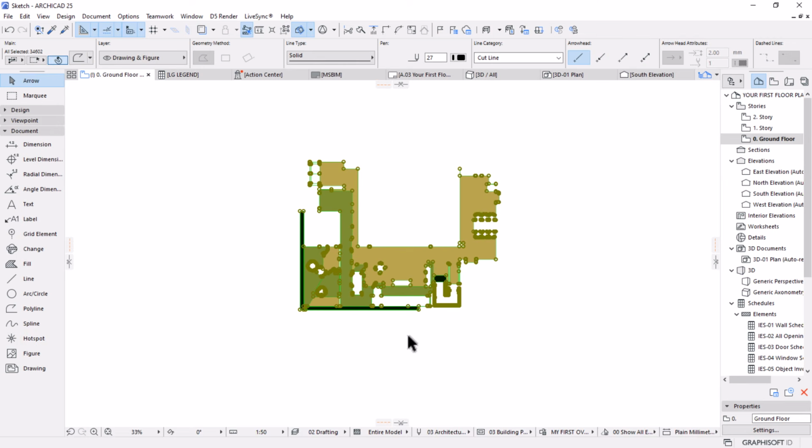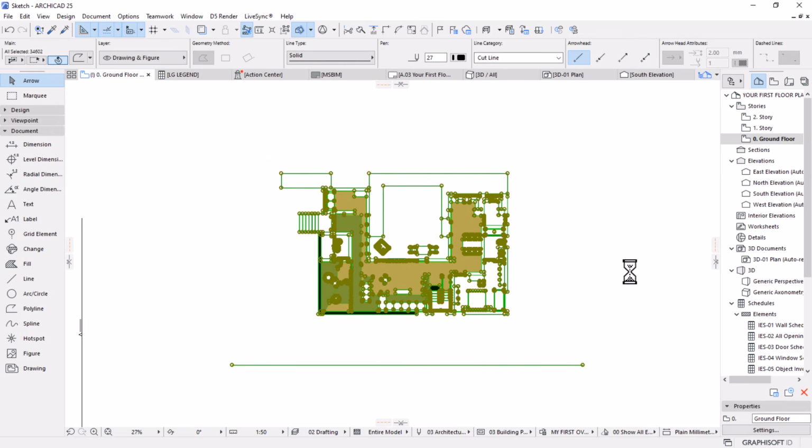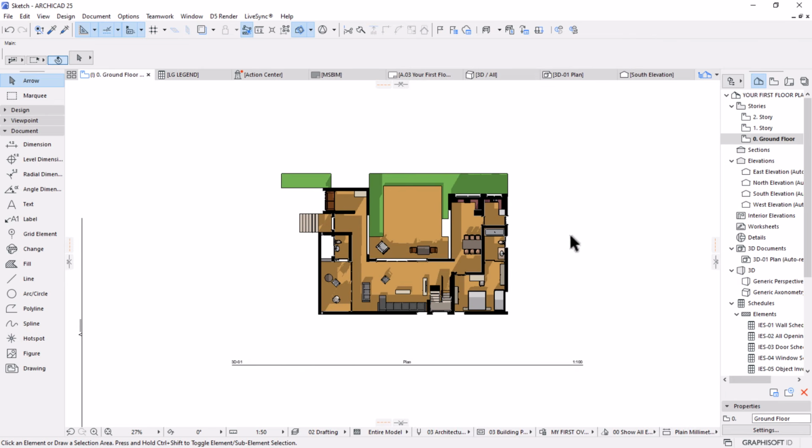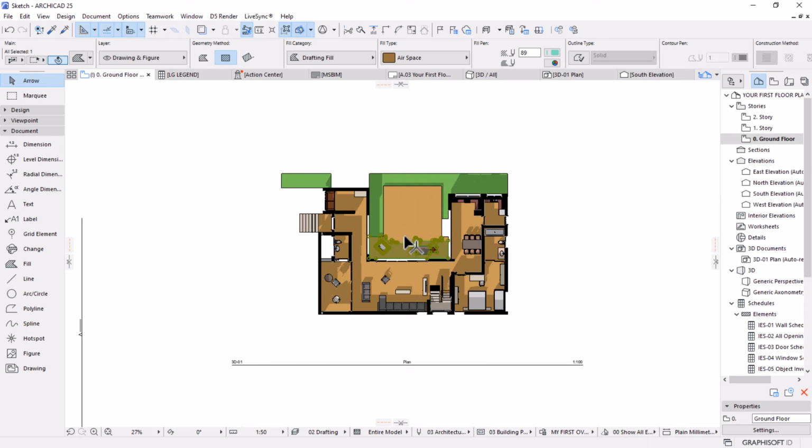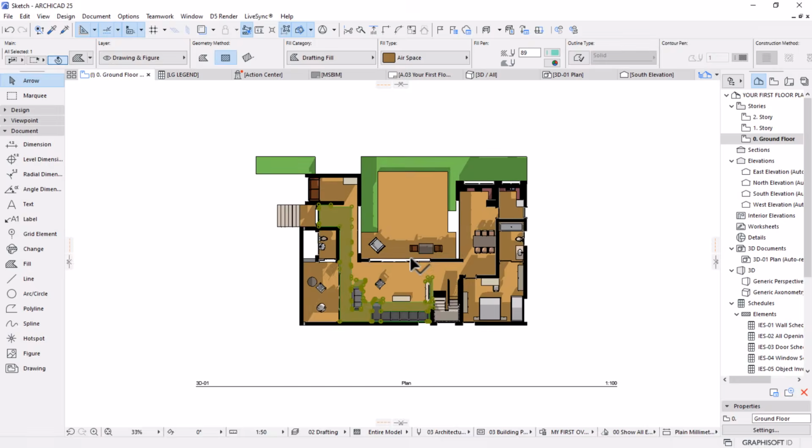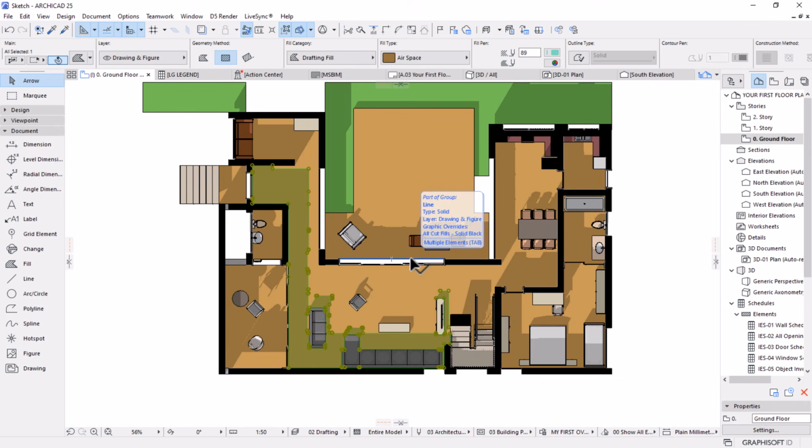What we need to do is to only select the shadows and then bring them to our actual floor plan. It looks heavy because there are a lot of fields on it. So what I need to do firstly is to unsuspend group, activate this as unsuspend group so that you can select these shadows. I can see everything's on one layer, so there's really nothing we can do in terms of separating it. I would hold shift to add all the shadows to the selection.